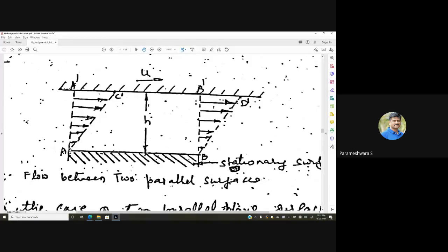And this fluid flow takes place by means of shearing action according to Newton's law of viscosity. So layer by layer the fluid flows. The particles which are associated with the moving plate will have maximum velocity, and the velocity of the lubricant comes down layer by layer, and it is zero at the stationary plate, I mean the bearing block surface. So this is the analogy of velocity distribution in case of hydrodynamic lubrication.